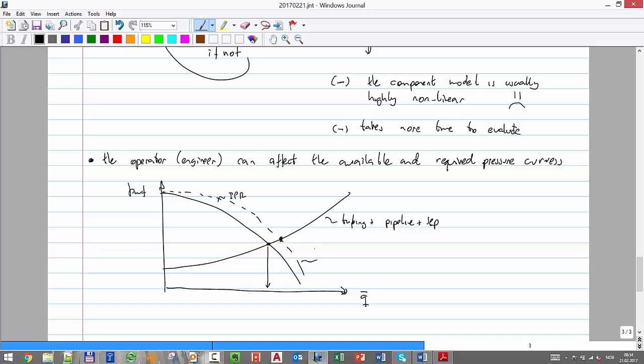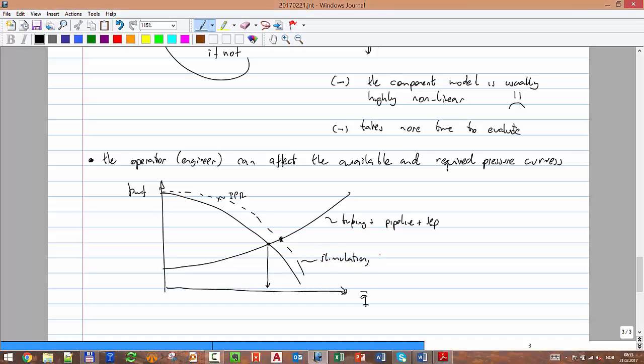That brings some memories. You have some stimulation, right? Acidizing, fracturing. You see what PI you have, if it's linear or, let's put it, squared, like for the gas back pressure equation. So you're trying to change that C and just increase it a little bit. You won't be able to make a very dramatic increase because you are bound to that point, which is given by the reservoir pressure. But you're able to increase the productivity a bit by some of these techniques.